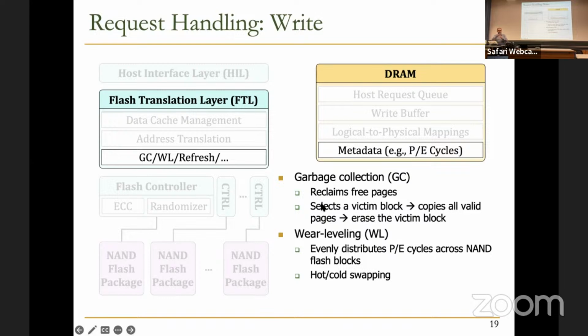You can just map things differently. If you just change the logical to physical mapping, you can easily implement wear leveling. But at the DRAM level, like the main memory, it's not easy, because you don't really have much of this logical to physical mapping. So that's why implementing wear leveling techniques for PCM as the main memory is not that easy either.